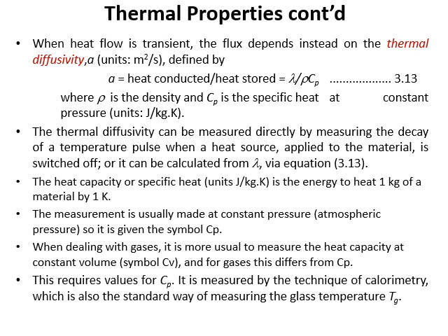The thermal diffusivity can be measured directly by measuring the decay of a temperature pulse when a heat source applied to the material is switched off, or it can be calculated from lambda via equation 3.13. So this one is called thermal diffusivity, where you measure the heat loss.